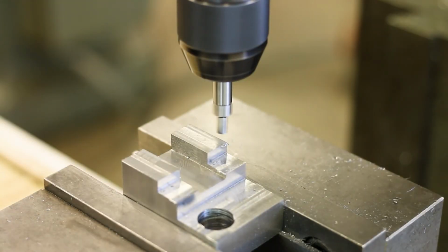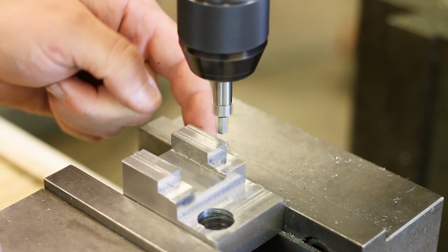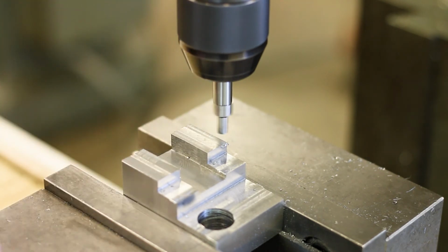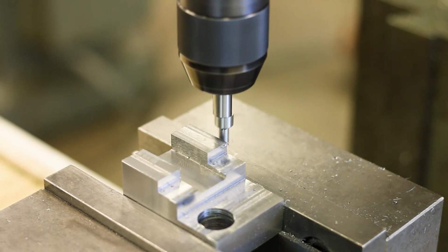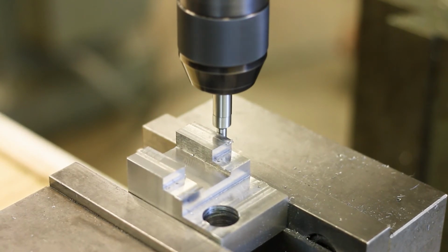Okay, go ahead and turn this on. Make sure that this edge and this edge are deburred because you don't want to be finding the edge of a burr, okay? You want to be finding the edge of the surface. Bring this down just a little bit like so. Okay, go ahead and bring the part into the edge finder.